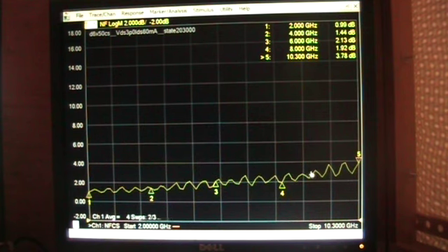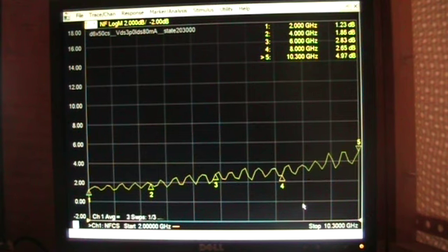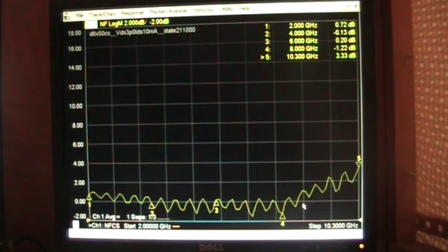Now you raise the bias and the noise figure can kind of take off at higher frequencies. Once all of these states have completed, the same thing happens. The tuner will move to a new state. The corresponding de-embed file will be dropped in.